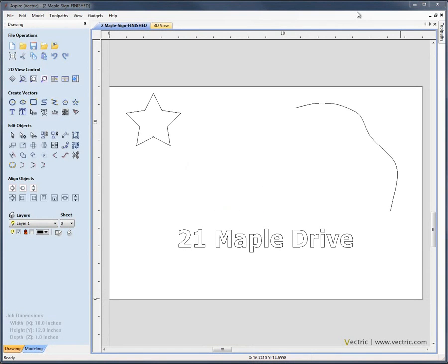In this video, we're going to give you a guide to working with the 2D view in Aspire. The 2D view is where you're going to draw, lay out and position different entities essentially in the XY plane, so basically to position them before you may go ahead and model or machine something. There are three main types of data that you'll come across in the 2D view.